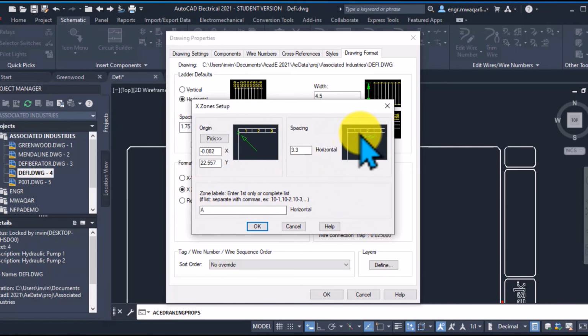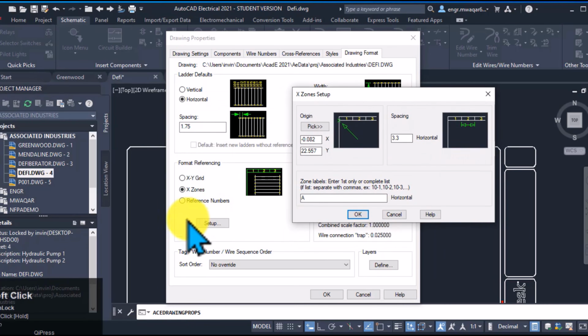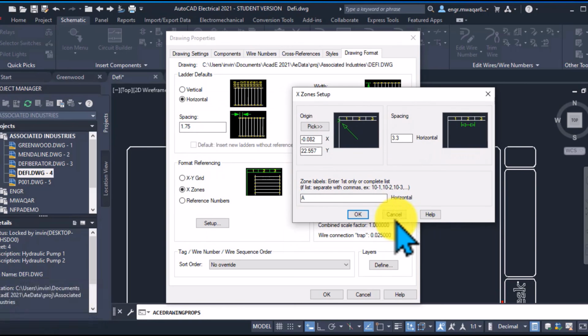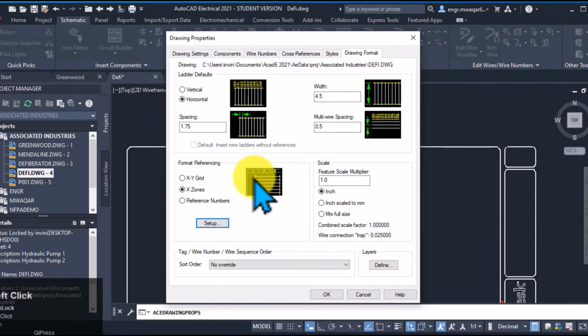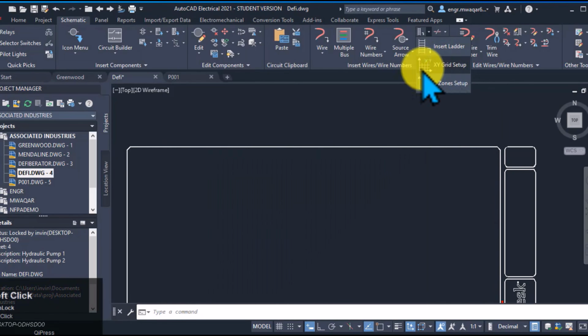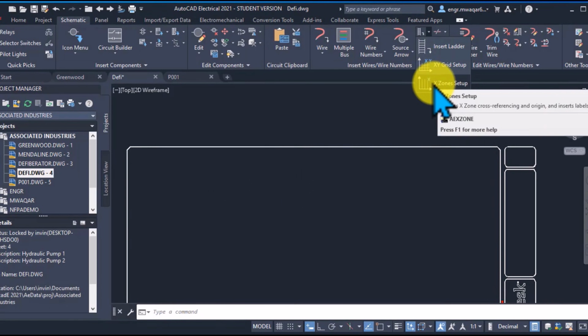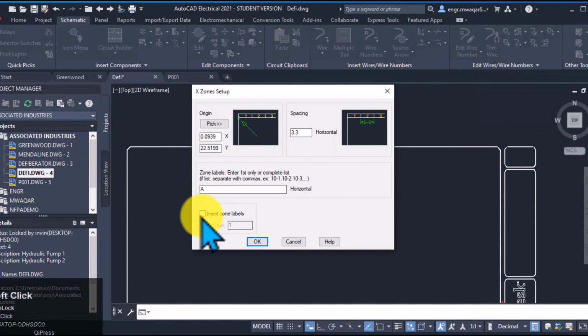In a ladder system, the address is the line number. But in a grid system, the address is the zone coordinate. And this all goes back to helping the maintenance technician. Exactly. When the tech sees CRB4 on an error readout, that tag tells them exactly where to look on the giant physical schematic printout. Go to column 4, go down to row B, there it is.